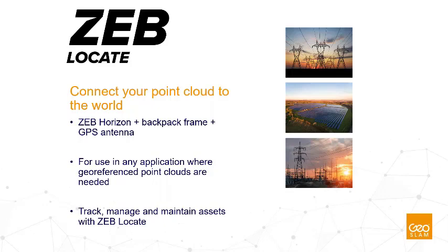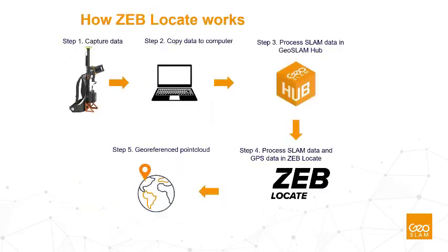We are now talking about post-processed data. This technology is not working in real time, but if you work with the GNSS antenna connected to the Horizon, you can then later in the software georeference very easily the data together with the point cloud.